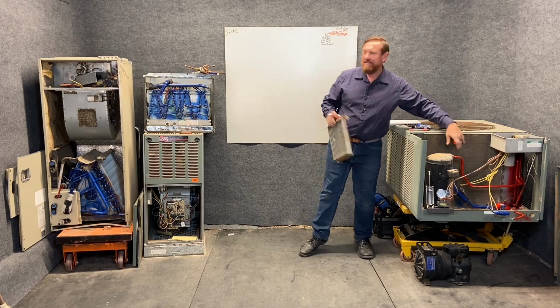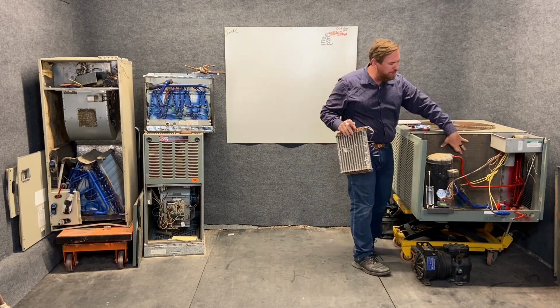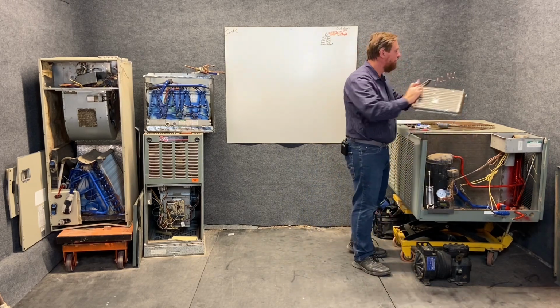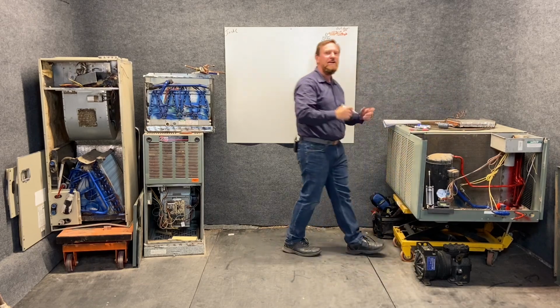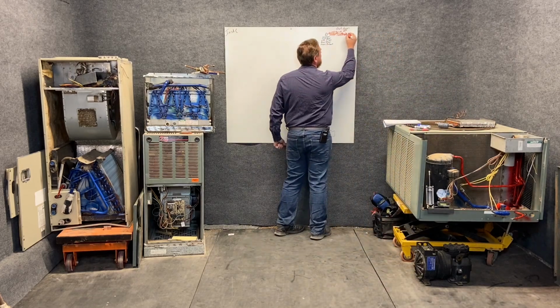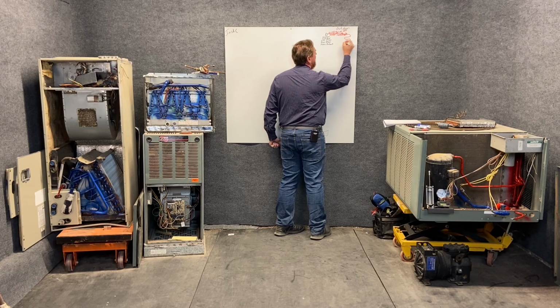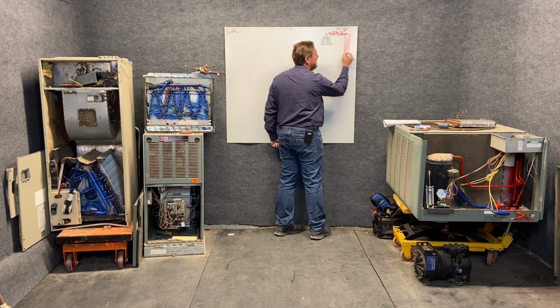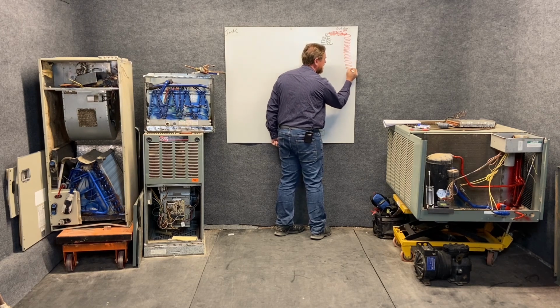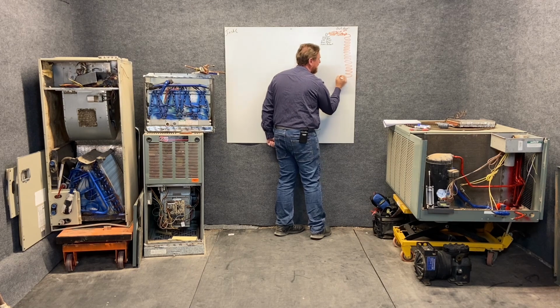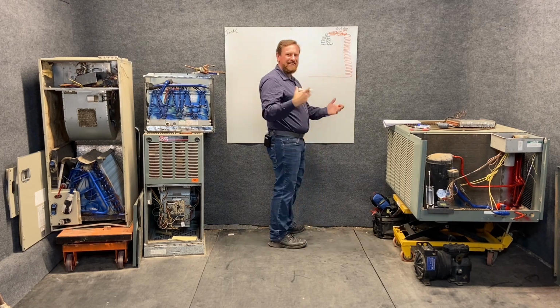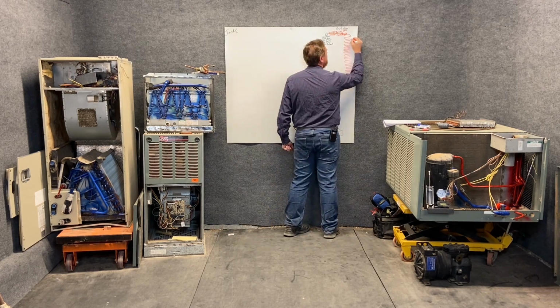So whatever you need to do when you're seeing us draw this condensing coil, I want you picturing this coil. And when you look at this coil, I want you picturing what we're drawing right here. So they are the same. They're not different. And we're going to go back and forth to represent the refrigerant flowing back and forth across that condensing coil. And then we're going to label this condensing coil.